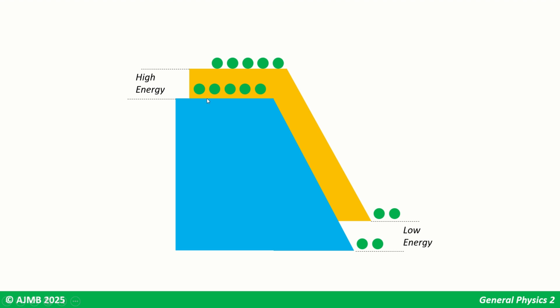So what I want to highlight here, what's important here, is whichever slide the charges choose to pass. This has a resistor on its own. This also has a resistor. They would have spent all of the voltages coming from the top to the bottom, right? So if the charges chose to slide here on the blue one, they have 60 volts here, and they would spend all of the voltages. And when they reach the bottom, they are going to have 0 volts left. Okay, energy was consumed all the way down through the slide.